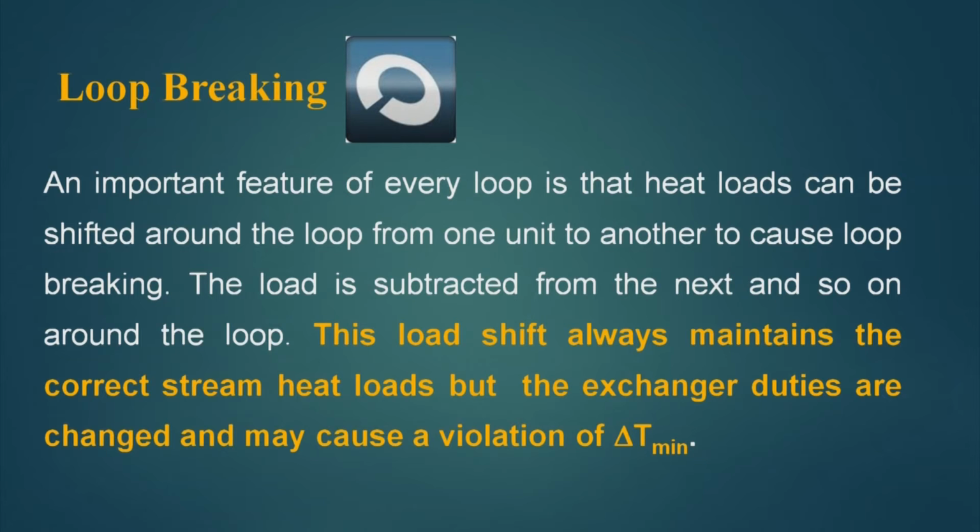The exchanger loads are balanced during this, which means the targeted temperatures will be achieved. But one thing we will see while doing this is that in most cases it violates the delta T minimum criteria, because we are passing heat through the pinch. We are violating the pinch criteria, that is why delta T minimum will be violated.